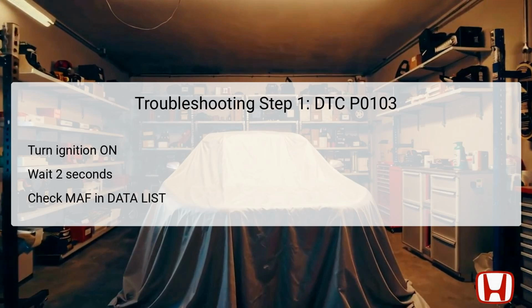If the readings meet these criteria, proceed to the next step. However, if the readings are below the expected values, it indicates an intermittent failure, and you should inspect the connections at the MAF sensor and intake air temperature IAT sensor, as well as wiring leading to the ECM/PCM. For the next troubleshooting step, ensure that the ignition switch is turned to the lock position, also known as 0. After that, utilize the HDS to jump the short circuit SCS line. This is important for any diagnostics involving the ECM/PCM.